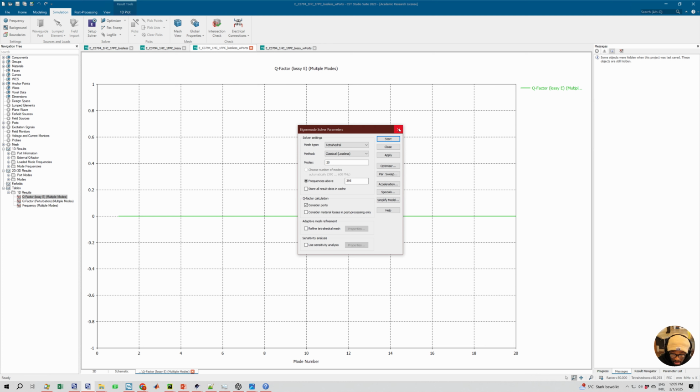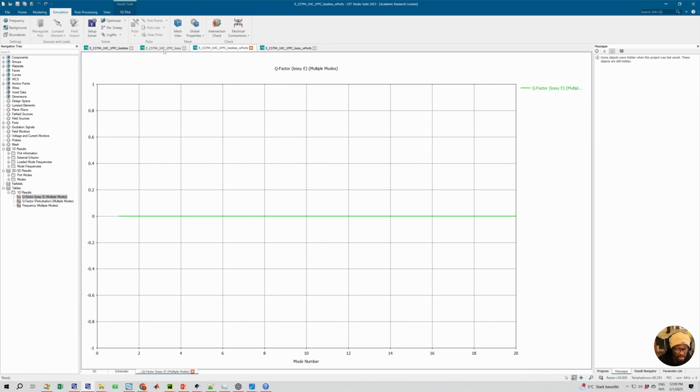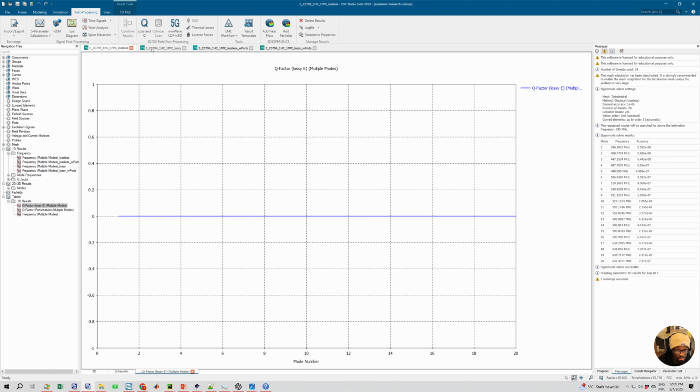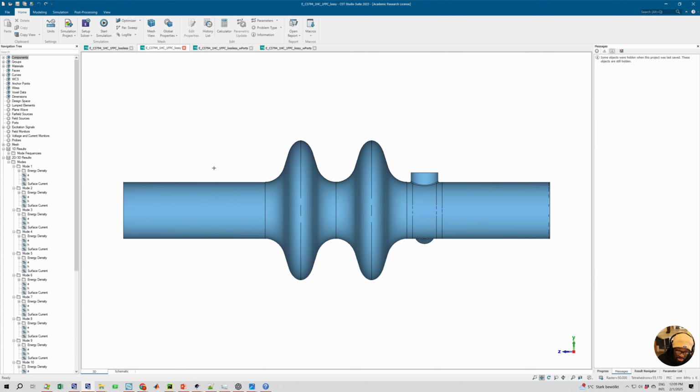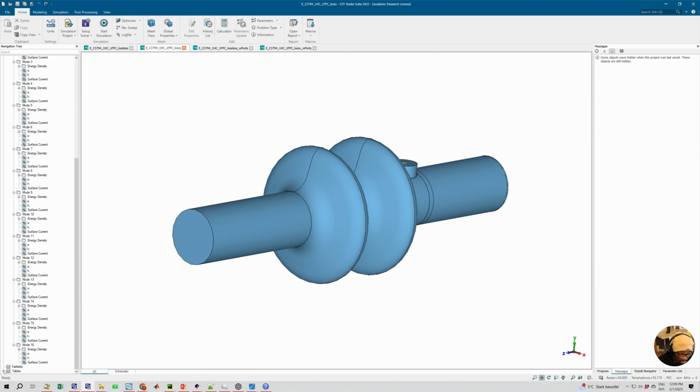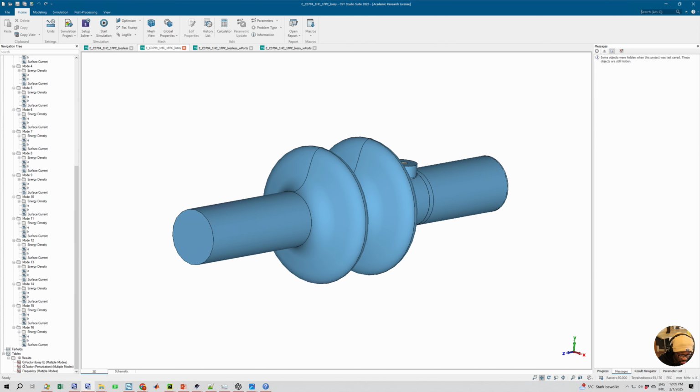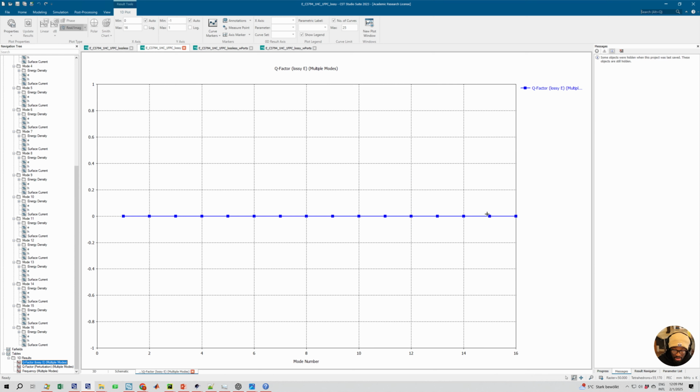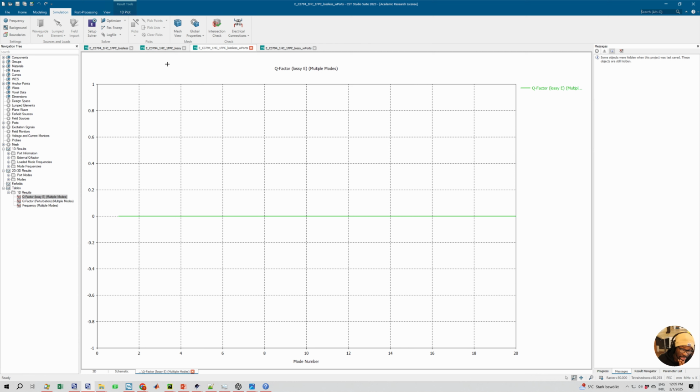What else? Then for the lossy, of course, if I run the lossy without ports, then it doesn't have anything to record, so the Q factor is also returned as 0. That is, the lossy eigenmode acts as your lossless if you do not have any ports defined. There are so many iterations to check, but I haven't checked this.